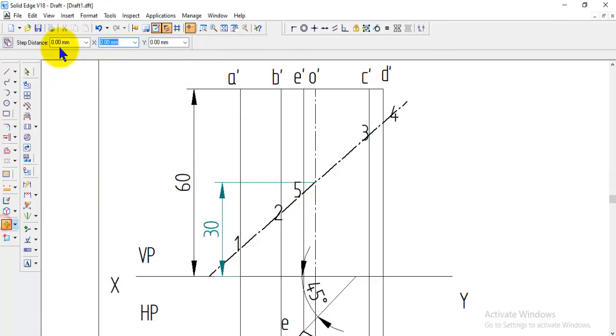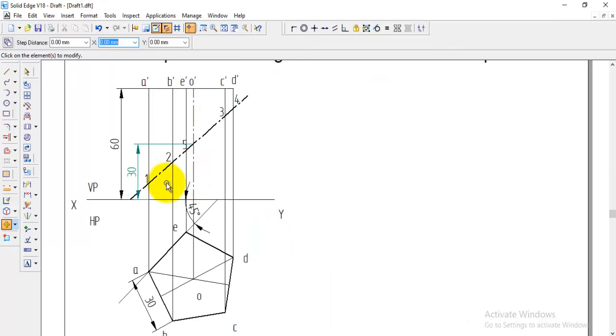Like this we can name the individual edges wherever it is cutting. We can give it in a sequential order on the sides. So it is cutting at 5 points. We already named all these 5 points. Now we will come to the development part.